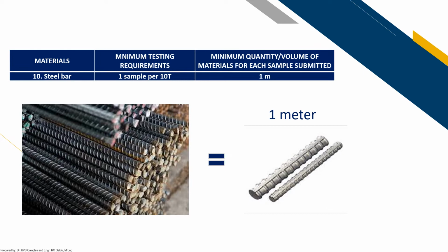Okay? Next is for your steel bar. So you need to obtain 1 sample per 10 tons, no, sa imong steel bar. And that sample would mean 1 meter. Kibale, you are going to submit, no, for quality test a 1 meter sample every 10 tons of your steel bar. So kung nakay 20 tons, so duha ka 1 meter ang imong isubmit, no, ana na siya.